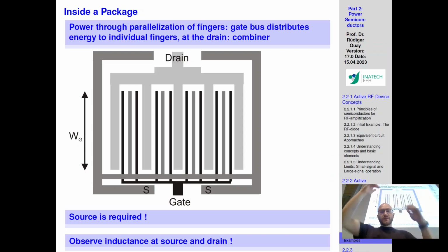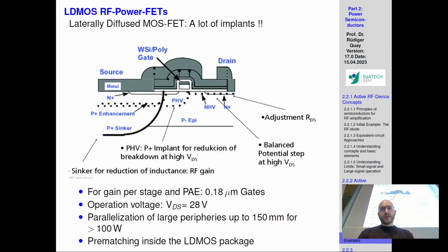We saw this finger structure for feeding the gate, and the source and the drain to contact the respective powers. We also saw an example of what you do when you take silicon-based technologies and adapt them for higher output powers. This was uniform doping with pre-doped areas, with increased layers of doping underneath the channel.